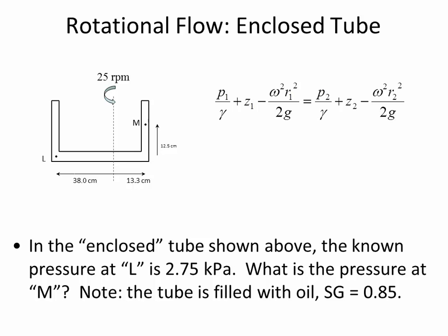So one way to cause boiling besides heating it up, or in the example they vacuumed out all of the atmosphere surrounding in that big glass bell. Another way you could cause boiling is by spinning something really fast. And in this case, since the U-tube is lopsided, we have an increase in pressure on the left, a decrease in pressure on the right. It's very possible that if you spin it fast enough, you could see cavitation.